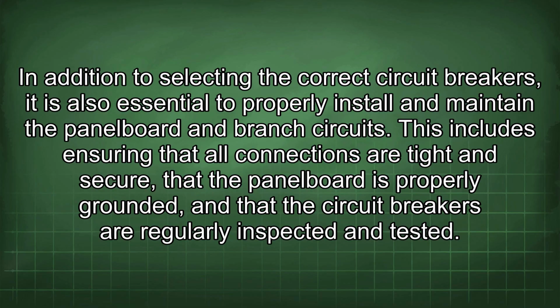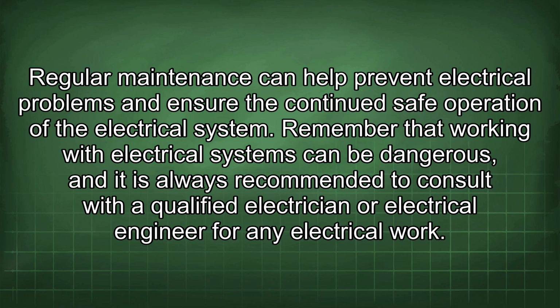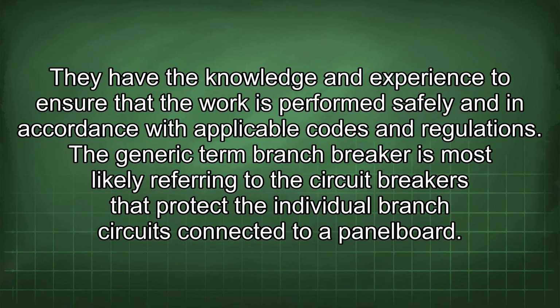In addition to selecting the correct circuit breakers, it is also essential to properly install and maintain the panel board and branch circuits. This includes ensuring that all connections are tight and secure, that the panel board is properly grounded, and that the circuit breakers are regularly inspected and tested. Regular maintenance can help prevent electrical problems and ensure the continued safe operation of the electrical system. Remember that working with electrical systems can be dangerous, and it is always recommended to consult with a qualified electrician or electrical engineer for any electrical work. They have the knowledge and experience to ensure that the work is performed safely and in accordance with applicable codes and regulations.